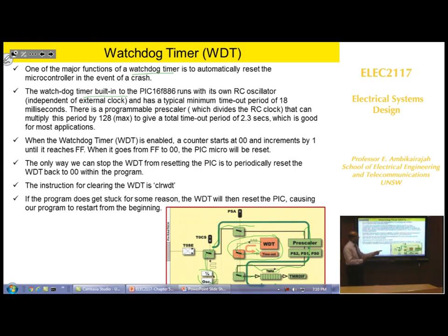Now we'll look at this. In the original table I showed you, the instruction cycle frequency is divided by 128. In this case, the oscillator clock frequency divided by 4 is the instruction cycle, divided by 128 maximum for a watchdog timer. Okay?